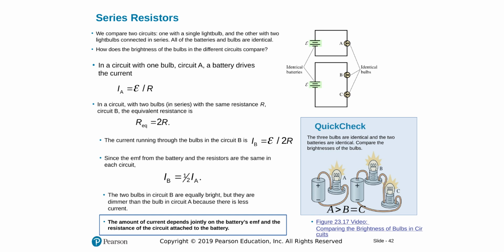Series circuits, again, they have the same current because we have one system here. I'll call this I total, the current drawn from the power source, and that will be passing through each. So I1 is equal to I total, and I2 is equal to I total. One can prove that the total resistance will be the resistances added.